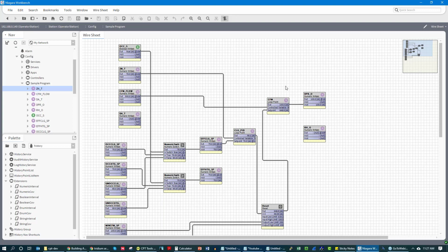All right, but nowadays, these supervisory devices have tons of capacity. We are not limited. Anyone who tells you that a BACnet or a building automation network is limited these days doesn't know what they're talking about. Legacy systems completely agree. The networks are limited by the device's abilities, by the field controller's abilities to send data to the supervisory device. Nowadays, though, our field controllers are almost as powerful as our supervisory devices, and BACnet MSTP has more than enough capacity when at the correct baud rate to send data, and IP definitely has capacity.